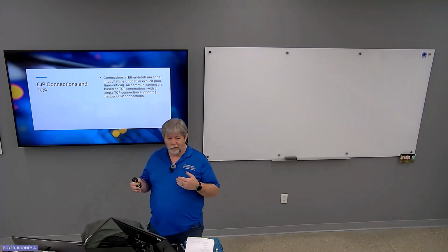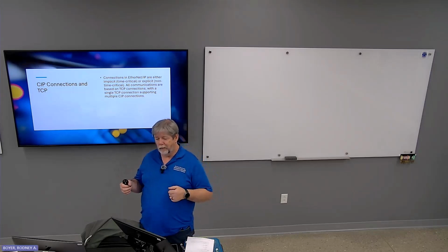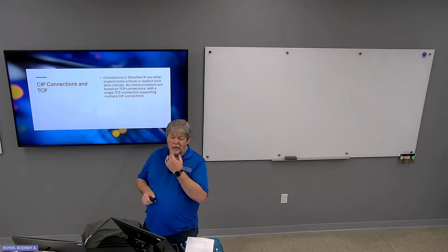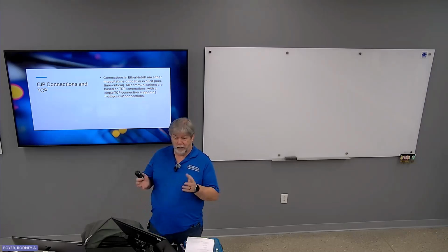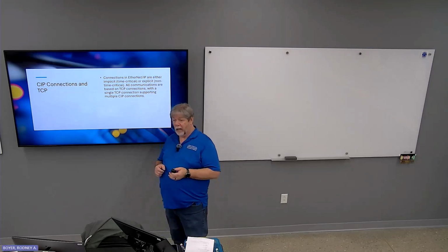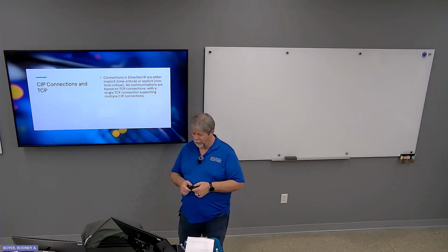Because if you're trying to rely on an Ethernet EIP CIP connection to tell you what the level is in a tank, or that kind of thing, and you use UDP, you're assuming the messages get there. They may not. So the tank can overflow and you never know it, or run dry and your pump would burn up or whatever. You can go either extreme.